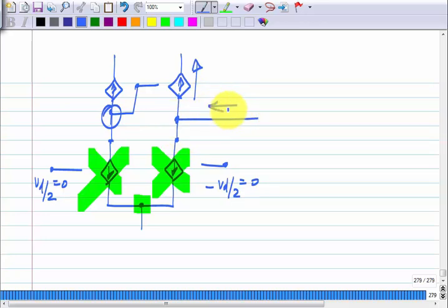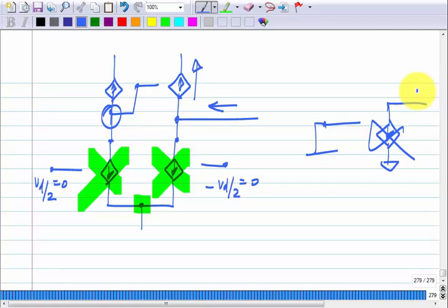I mean, this is not very surprising. If I have modeled the transistor with only a GM and no GDS, what will be the Norton equivalent resistance? Infinite, okay. If I set VGS to 0, this will go away and I will have infinite resistance. So, if there is no GDS for any of the transistors, the output resistance will be infinite, okay. The differential pair will behave like an ideal incremental, controlled current source, that is all.